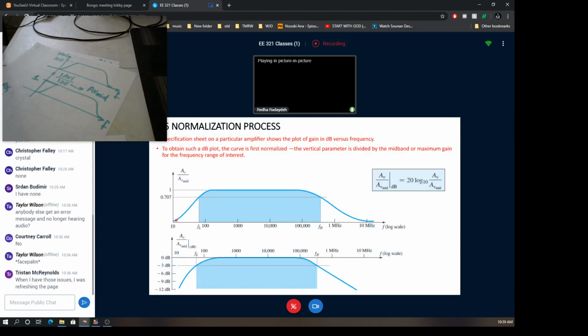If you want to sketch this in decibel, let's say, and the maximum value was 100, the 100 is something very big like this. So sometimes if the gain is very large, in order to reflect that high gain accurately, you have to expand the sketch very wide, right? That's why the normalization will always help us to sketch them to scale